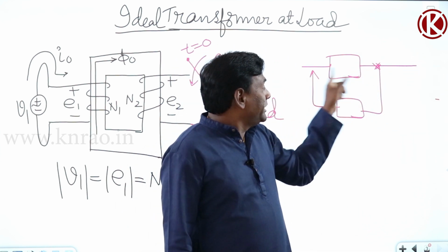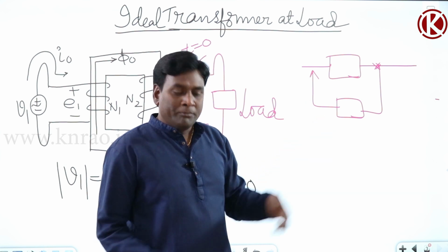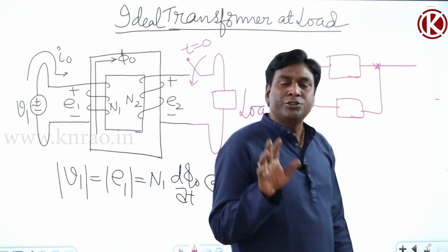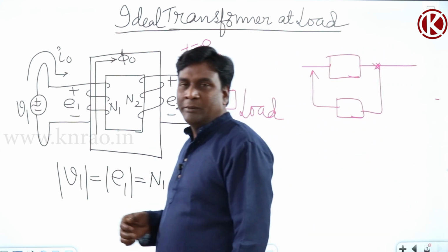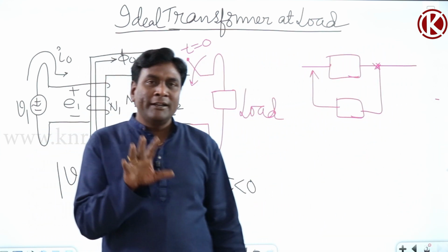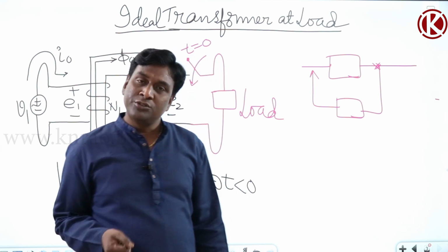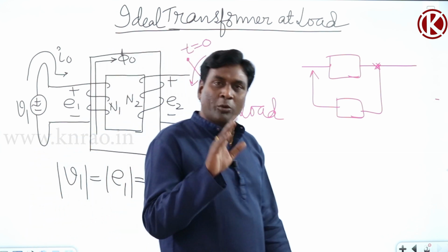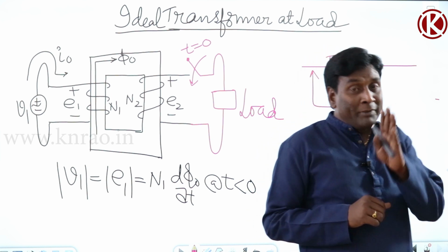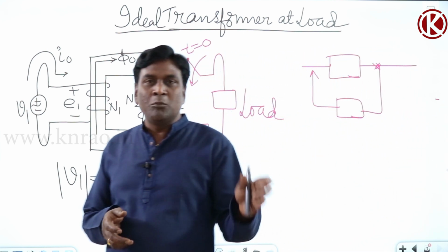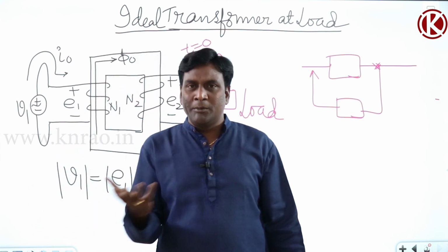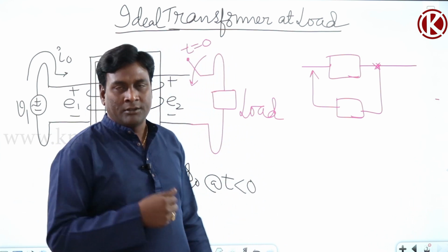Now if you think of the feedback path, one thing I'll tell you: measuring instruments, ammeter, voltmeter, wattmeter, energy meter, whatever it may be. At least analog measuring instruments and our machines have the same operating principles. In machines, the way torque is developed in a motor, in the same way torque is developed in measuring instruments, that is deflection torque.